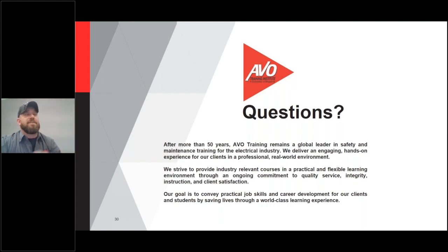Let me fix one thing first. We throw that hipot word around. I want people to understand that Hipot is a trademark name of a piece of equipment. So when we talk about hipotting, we're referring to a piece of equipment. What we want to call that type of test is an overvoltage withstand test, because that's essentially what we're doing. We're hitting it with an extreme overvoltage.